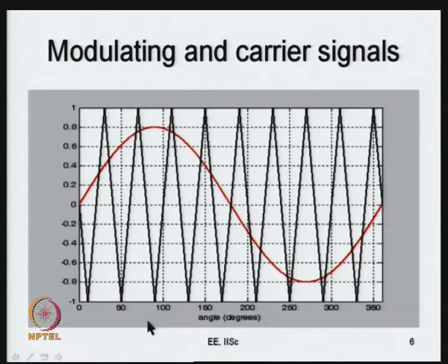In very high power levels, this could be lower. For example, where you use IGCTs or GTOs, this carrier frequency could only be a few hundred hertz. So, we have a model, and for all purposes of the study, we regard this carrier signal as a high frequency signal whose frequency is much higher than that of the modulating signal, so that in one carrier cycle you can regard the modulating signal to be almost flat. Any change that you have can be ignored now.